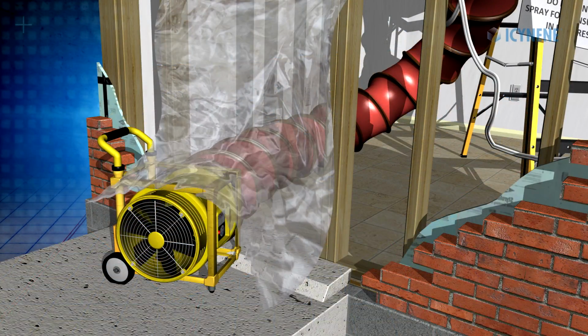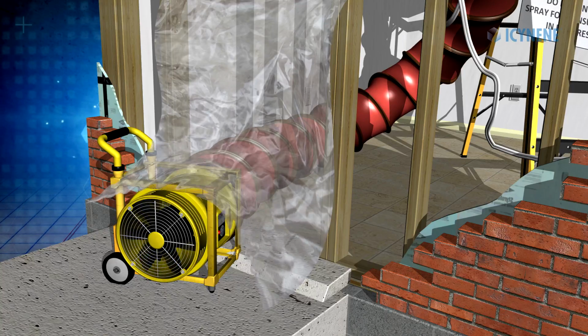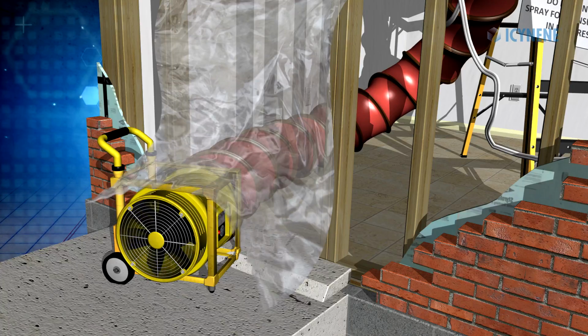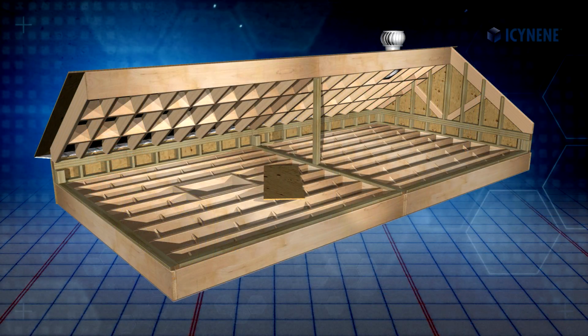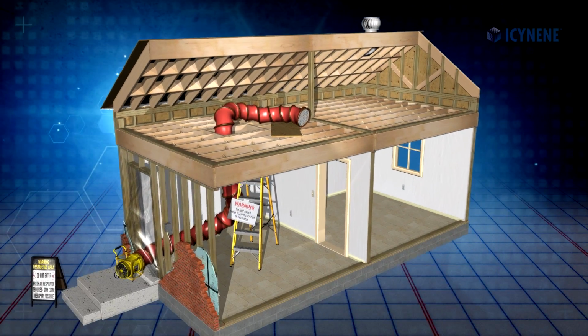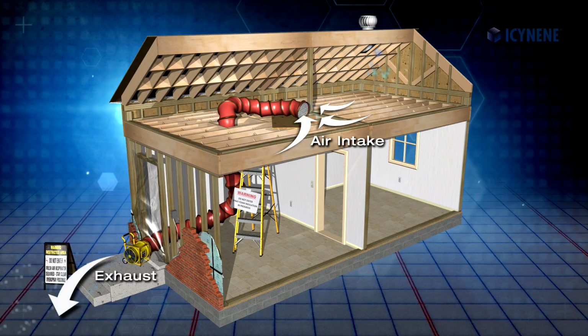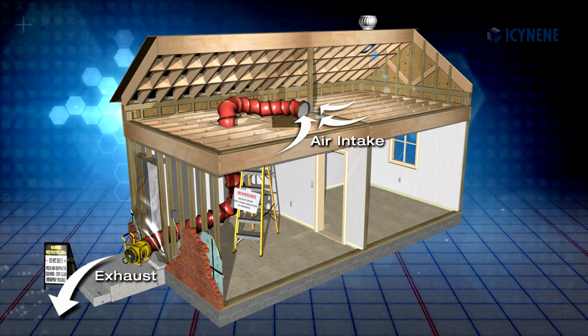Now that you have the required cubic feet per minute, you will need to obtain a suitably sized fan or fans capable of delivering the desired ventilation rate for the required re-entry and re-occupancy traffic. Make sure that the fan is positioned such that the air is drawn away from the spray area and ventilated to the outside in a safe location.